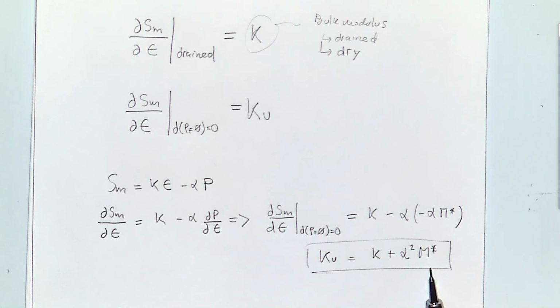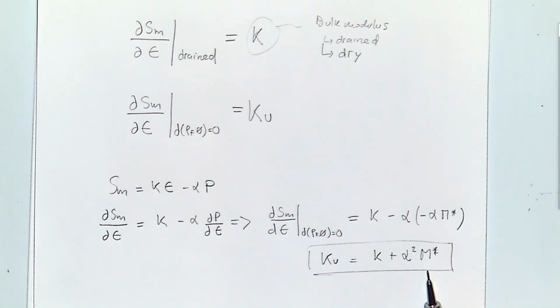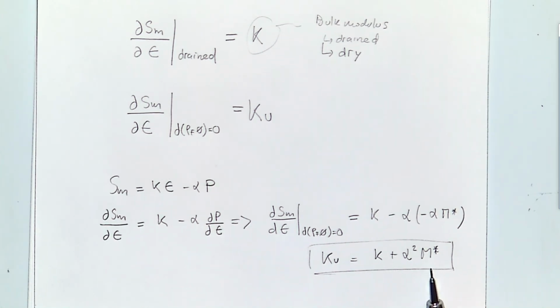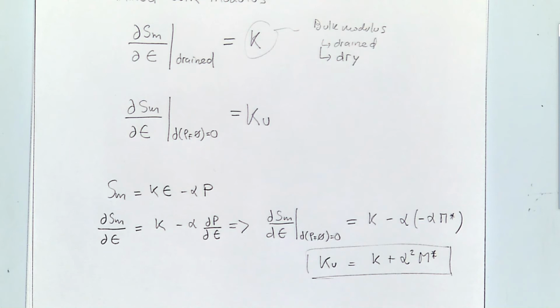For many experiments, especially in shales, people measure Young's modulus, measure bulk modulus, but the time that you need for the fluid to get out of these shales is very long. It can be sometimes months, and sometimes you cannot run a test in months.